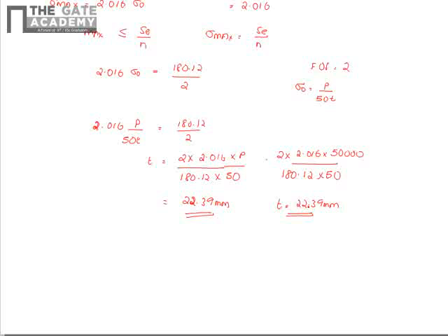So this way we can do the design of components if we know the stress concentration factor clearly. So the fatigue stress concentration factor, unlike for static loading, depends not only on the theoretical stress concentration factor but also depends on the notch sensitivity factor, which is nothing but the factor which tells how sensitive a material is to presence of notch.